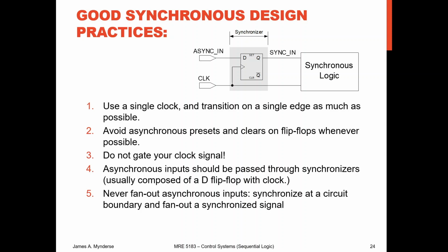Don't gate your clock signal, obviously. And so all your asynchronous inputs are going to run through your synchronizers, and then your synchronized versions are then going to be sent to the various logic inputs. You don't fan out, you don't distribute your asynchronous inputs. They all have to be synchronized before they move on. So you're running everything through your logic. Now it does create delays, but it's not huge delays.